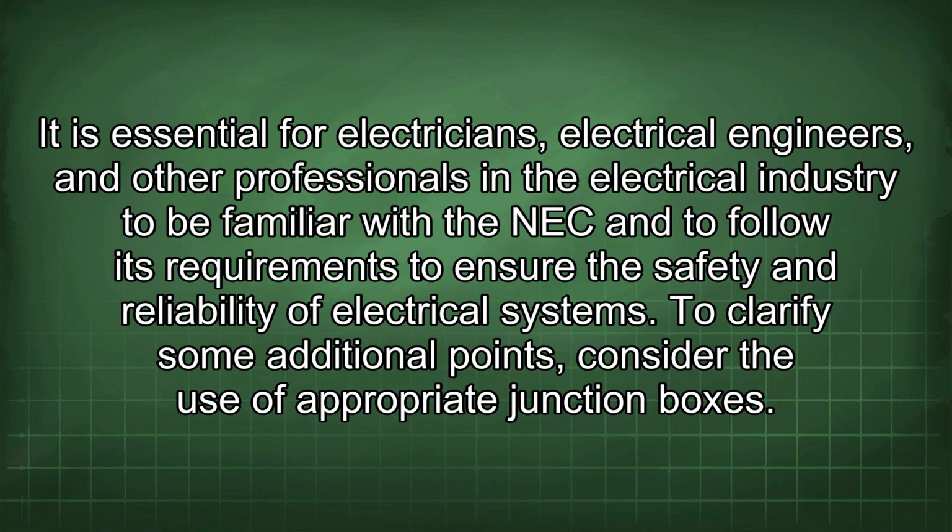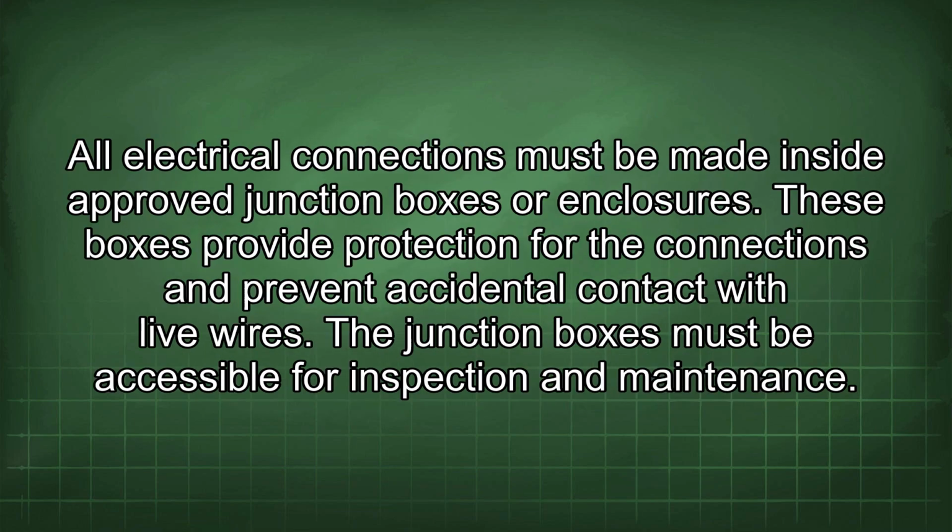To clarify some additional points, consider the use of appropriate junction boxes. All electrical connections must be made inside approved junction boxes or enclosures. These boxes provide protection for the connections and prevent accidental contact with live wires. The junction boxes must be accessible for inspection and maintenance.